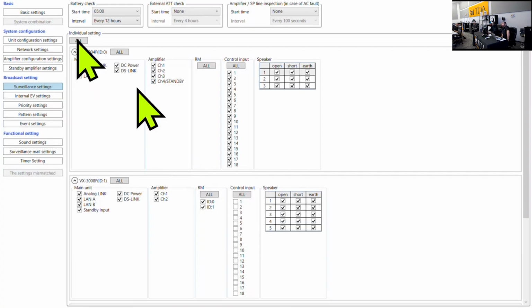I believe it also checks the internal resistance of the battery. It might also check the discharge, like how the battery check usually performs. You temporarily disconnect power and see how the discharging rate is going. So there's some algorithm for how it's performed, but usually you should perform this during less load on the system, like during the night, for example.